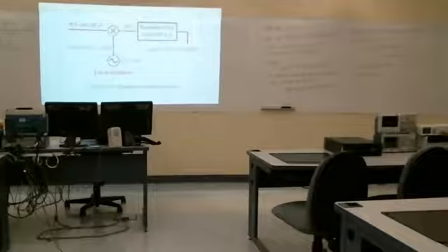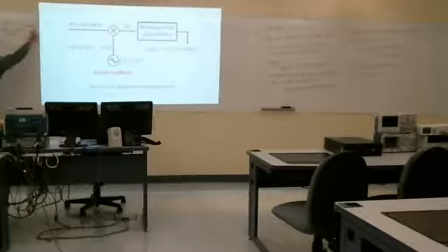I multiply the Fourier transform of my input times my frequency response. So I've drawn, you know, kind of an ideal bandpass filter here. But then what we would get out is just the one station we're wanting to listen to. Okay, at 1020, all the others would be filtered out. And then I'd envelope detect that, you know, for a standard AM radio.